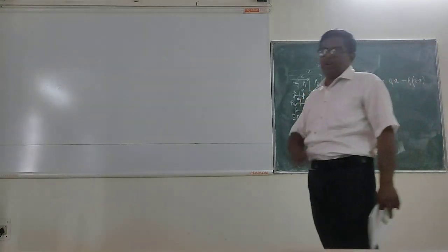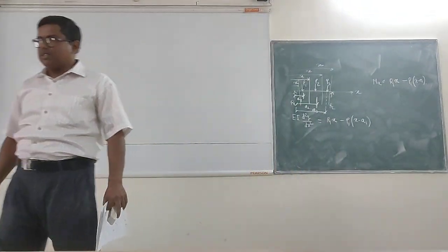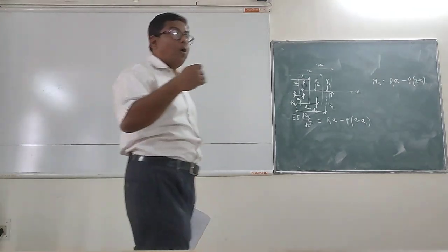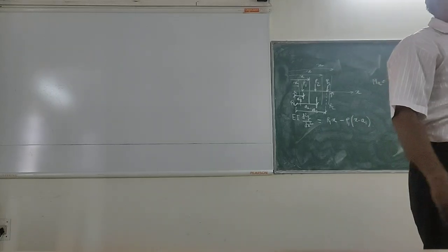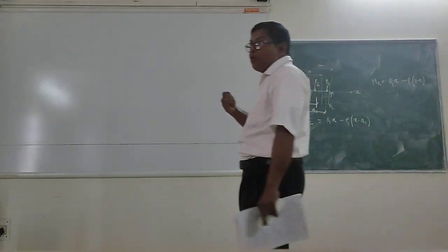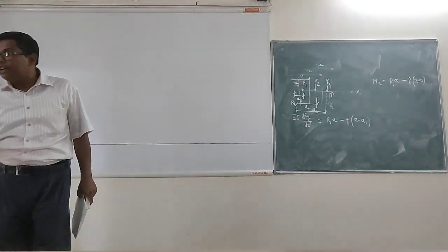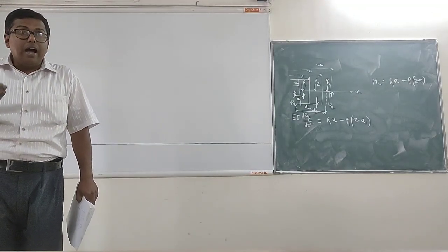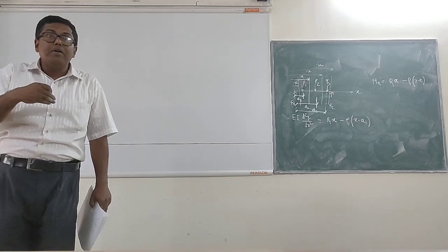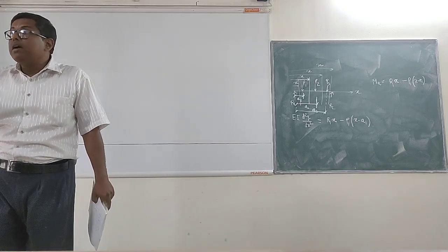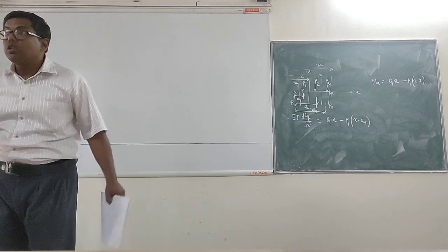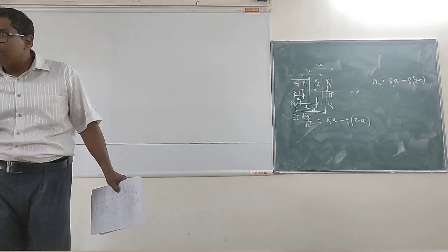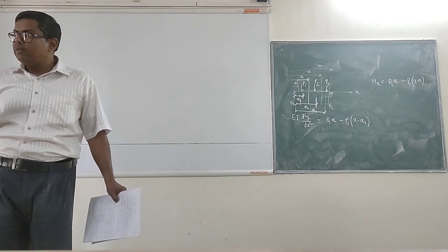This is what is Macaulay's theorem in the deflection calculation. Accordingly, I find out the value of the constants. When I put the boundary conditions in, I should find out what the conditions are, and when I put the values in, all the other terms will become either negative or 0. The negative terms and the 0 term should be neglected. Have you understood? Is it clear to everyone?